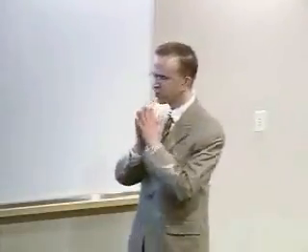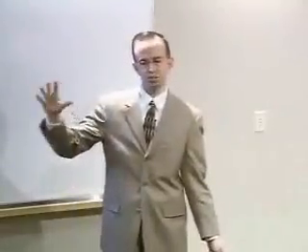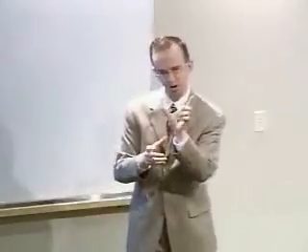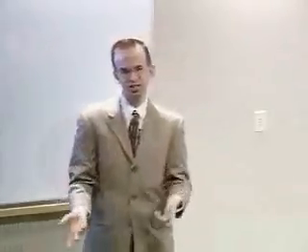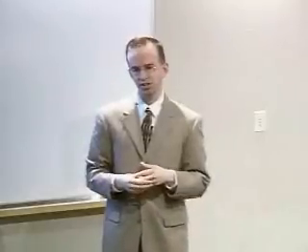What is the number? So right now there's a question of where you actually compute the fading parameters. Right now we're doing it all out on that PC. And so we're using an Ethernet connection to send out the scaling factors to the emulator. So that's sort of our bottleneck. Our future implementations are going to push that computation into the FPGA itself so that that's not as much of a bottleneck.